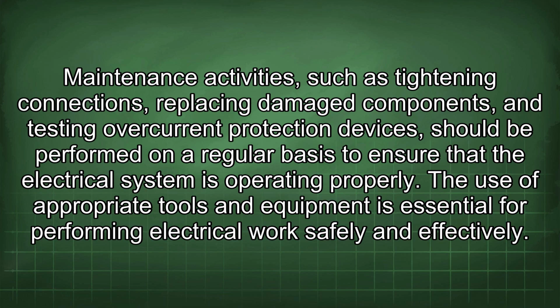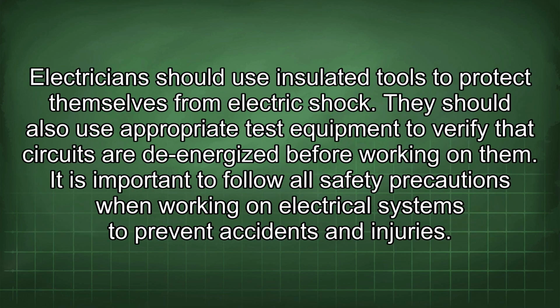The use of appropriate tools and equipment is essential for performing electrical work safely and effectively. Electricians should use insulated tools to protect themselves from electric shock. They should also use appropriate test equipment to verify that circuits are de-energized before working on them. It is important to follow all safety precautions when working on electrical systems to prevent accidents and injuries.